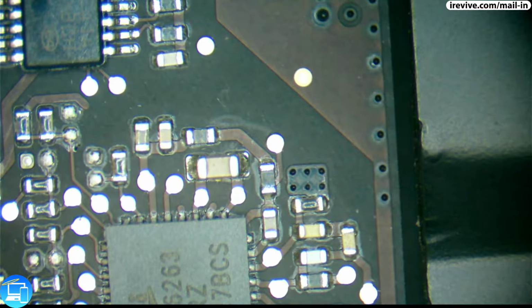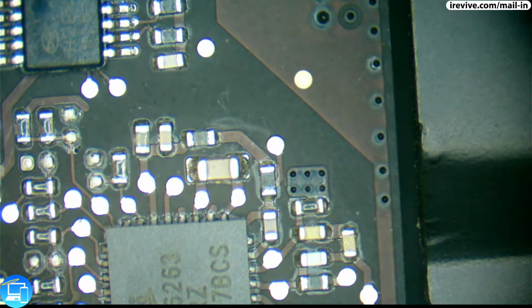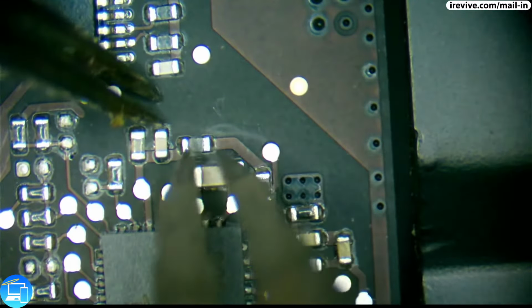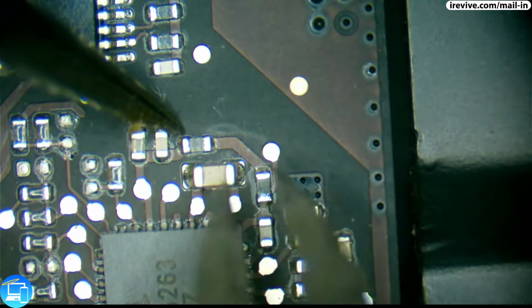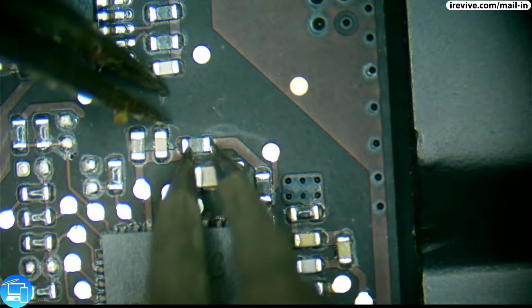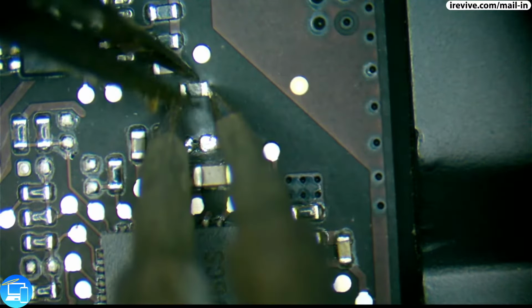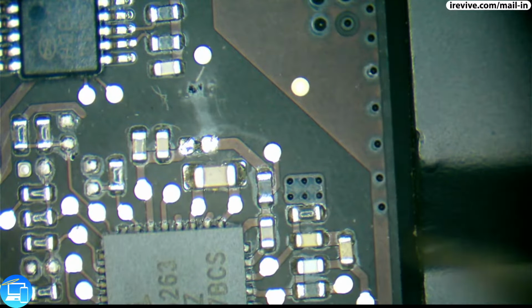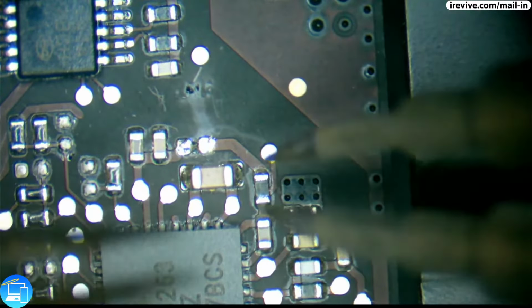And I have some hot tweezers here. It's just soldering iron tweezers that we are going to use for plucking these off. So once we hear a beep, this is going to be hot enough to where I can just simply touch this and it's going to come right off. There's no ground connection, so I really don't have to worry about heat. Just lightly touch the resistors, and they're gone.